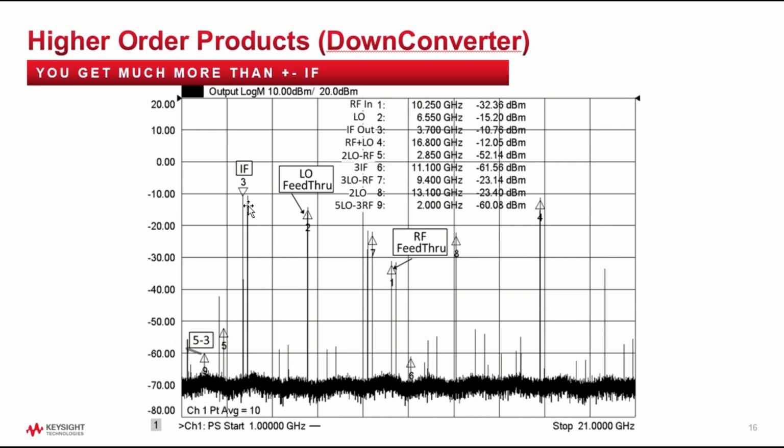And in this plot, what I've done is I've shifted the signal from its initial input of 10.3 down to 10.25. So I shifted the signal here, and what I see is the IF signal also shifts down. The yellow signal didn't shift, of course, because I'm not moving it. And I see this little signal here. That signal is the image of the second order term.